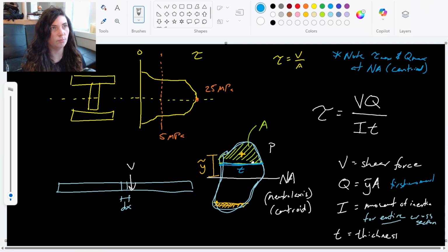First moment of area. And then we'll look a little more in depth at how we use this exact shear stress equation so that we can calculate our maximum shear stresses to make sure that our beam is not going to fail. We're also going to be able to use this to design the cross-section and design fasteners. So if we want to glue it or use nails or bolts, we're going to be able to use this equation to do a little bit more detailed design.